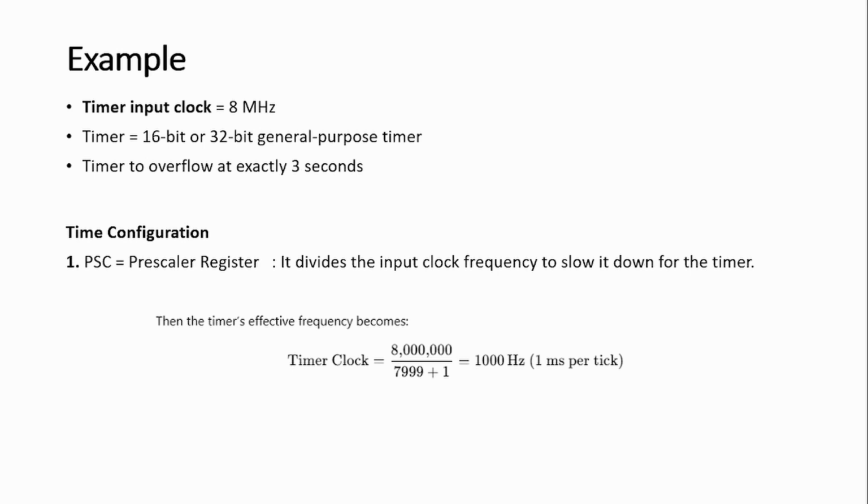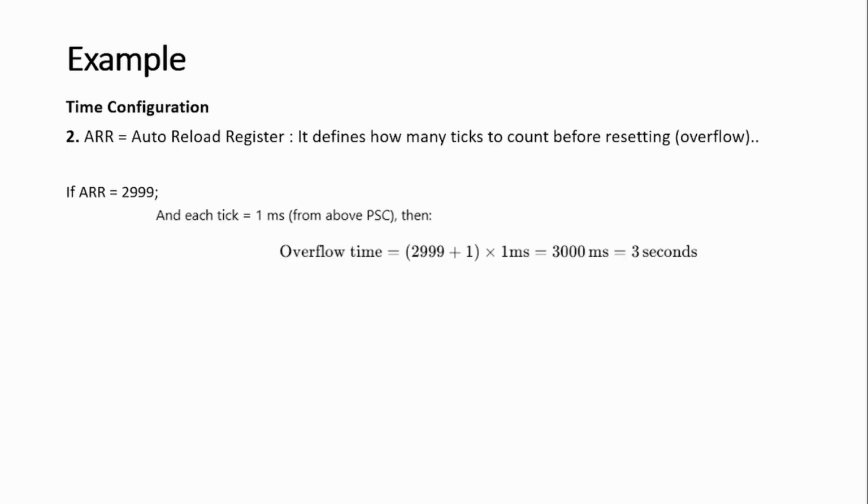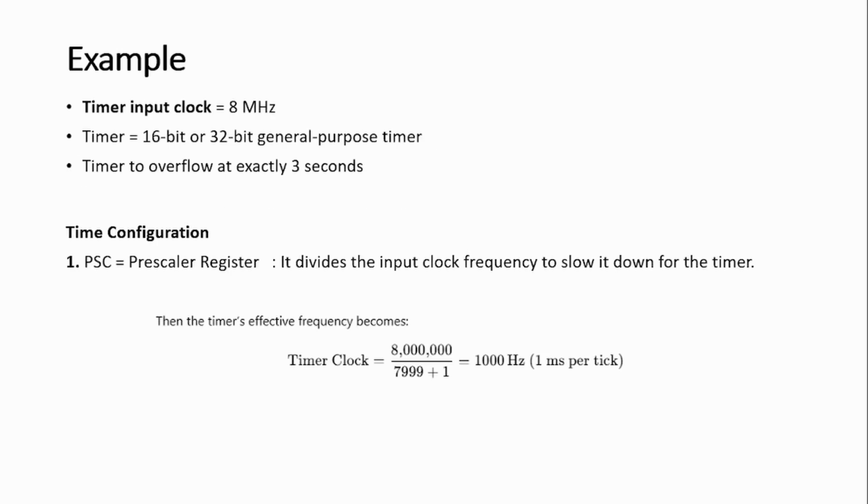Let us say you decide that 20 second is my overflow, so after 20 second you can do certain task. So a timer is like that only. But to decide that overflow, you have to configure it, and for that you have two registers. One is a prescaler register, which we are also going to configure in our STM32 program, and another register is ARR, the auto reload register.